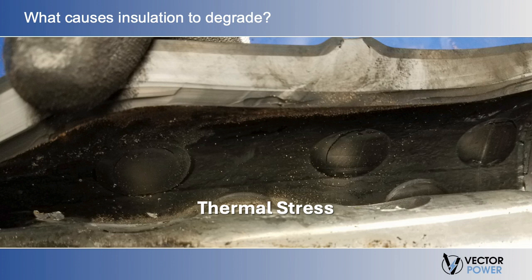Continuing on the topic of thermal stress, heat dissipation is an important factor when considering ampacity. If heat cannot dissipate, the insulation begins to heat up and can lead the insulation into a thermal runaway. For example, the thermal resistivity, or the rate at which a specific material can resist heat flow, differs for each cable component and the medium around it, which can be ductwork or the environment. If the thermal resistivity of a material is low, then the heat can dissipate quickly.